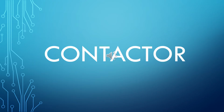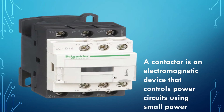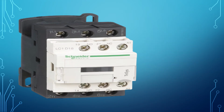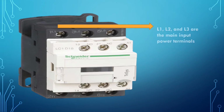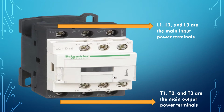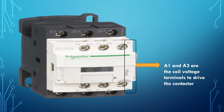Contactor. A contactor is an electromagnetic device that controls power circuits using small power control signals. L1, L2, and L3 are the main input power terminals. T1, T2, and T3 are the main output power terminals. A1 and A2 are the coil voltage terminals to drive the contactor.